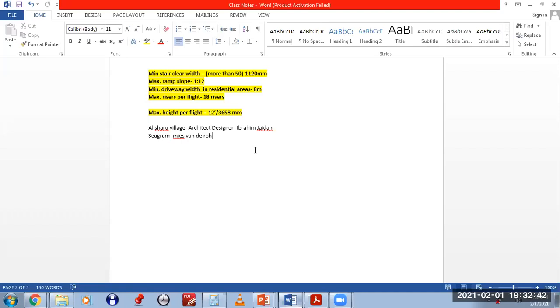It's a bond having courses of headers between every 5 or 6 courses of stretchers. Not 3, every 5 or 6. Okay.